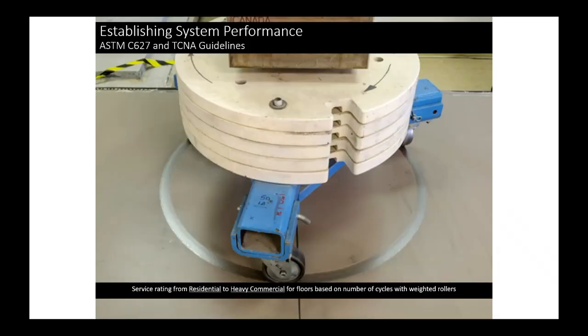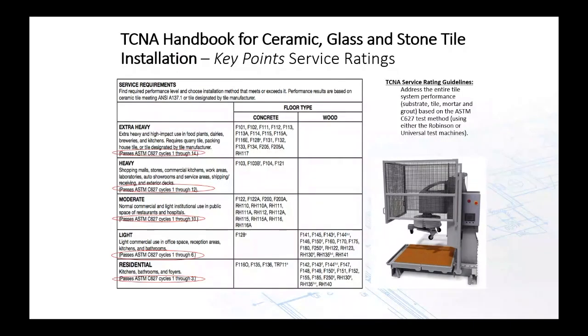What really happens here, the easiest way to explain it, is if I took a concrete slab, which is typically the Robinson substrate, and I put quarry tile with a latex modified mortar on it, and got it installed correctly, fairly level, no lippage, grouted it, quarter-inch joints, and so on, I could pretty much expect that to go to a heavy or extra heavy rating system. That means that it's rotated through 14 cycles.